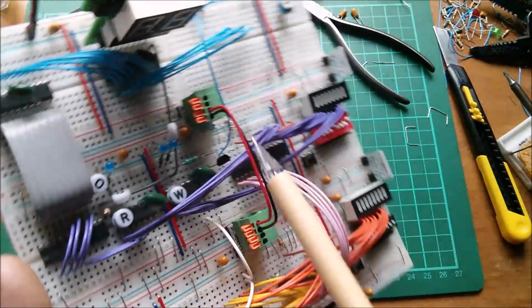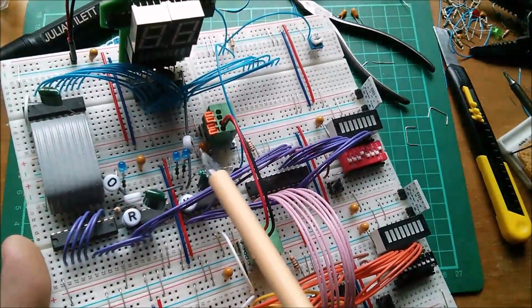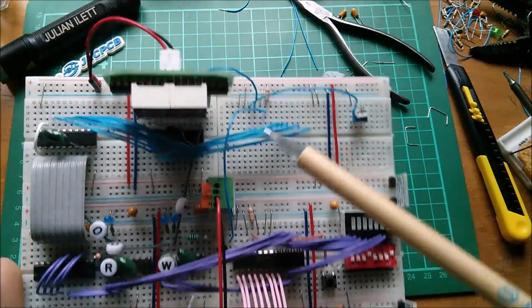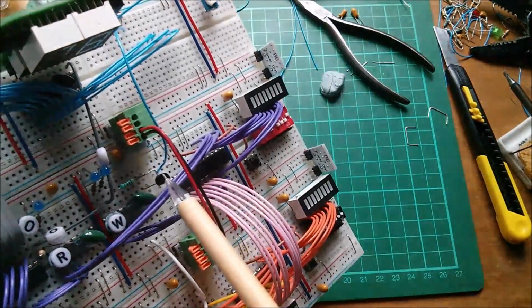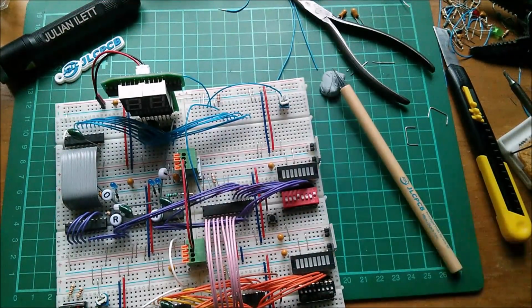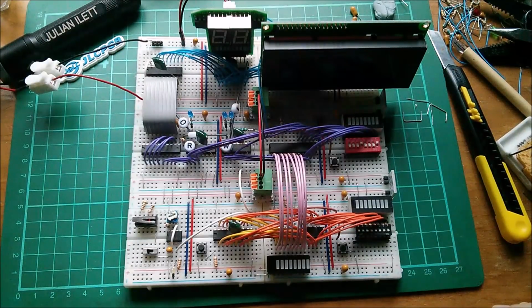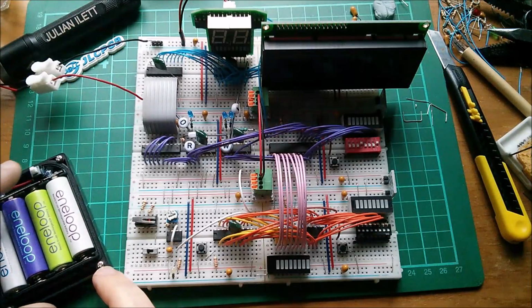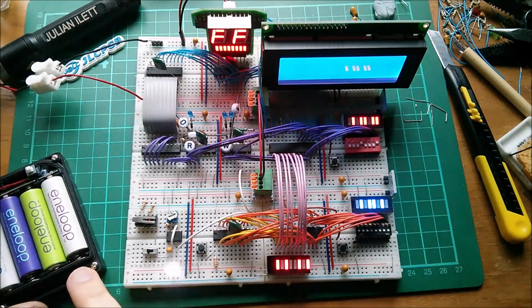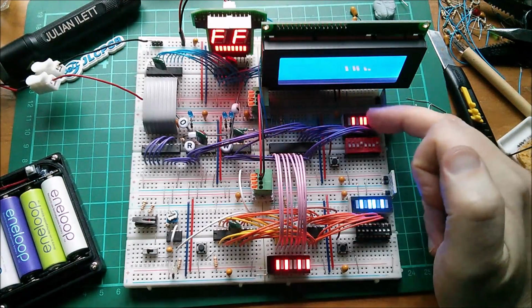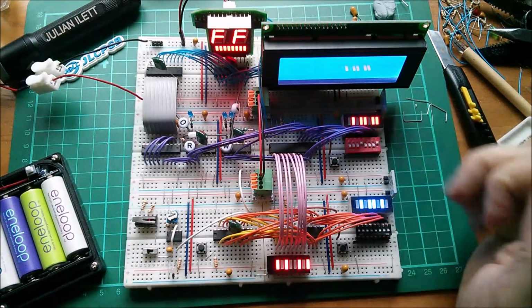I've got my transistor here on right number 2, and I've got a 1K pull up there because of course this transistor only pulls down. So let's see if that works. I must admit, I've only got the odds at about 50-50 at the moment. Not feeling terribly hopeful, but let's switch on. And that's okay. That's just a reflection in the display of these LEDs. I'll have to sort that out.